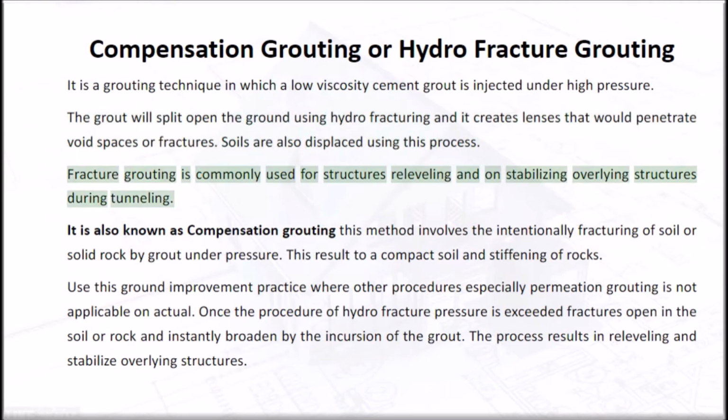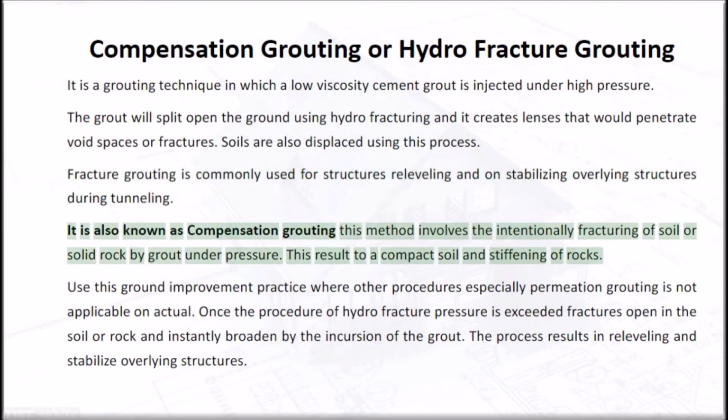Fracture grouting is commonly used for structures releveling and on stabilizing overlying structures during tunneling. It is also known as compensation grouting. This method involves the intentional fracturing of soil or solid rock by grout under pressure. This results in compact soil and stiffening of rocks.